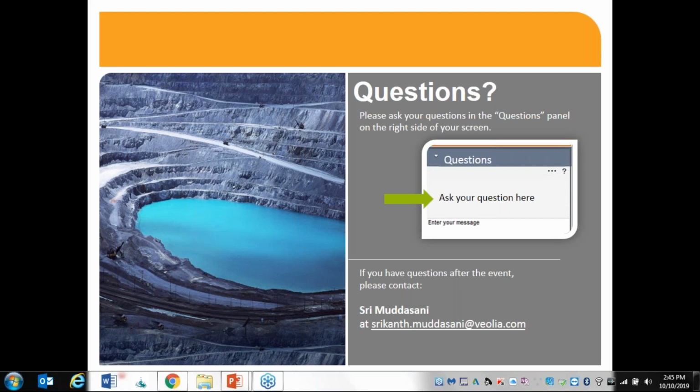Another one that came in is, what is the optimum pH, reaction time, calcium to sulfate, and aluminum to sulfate ratio for ettringite?